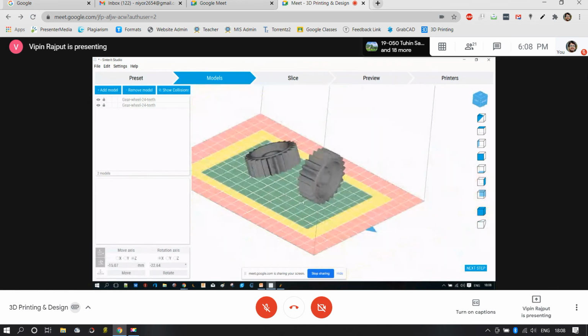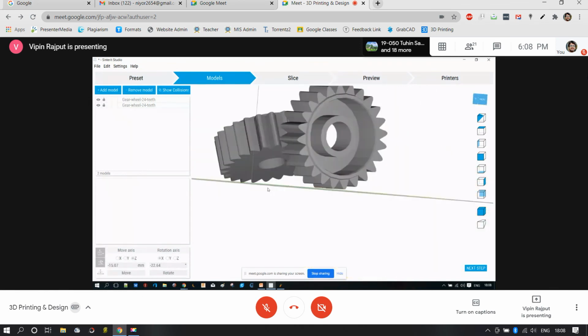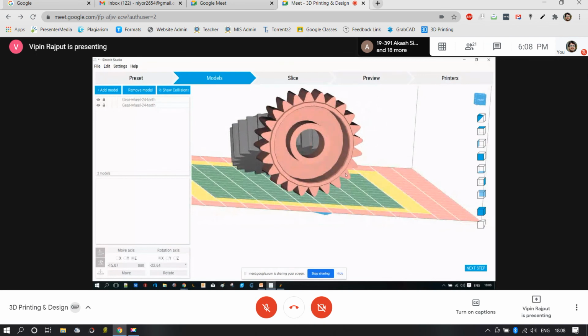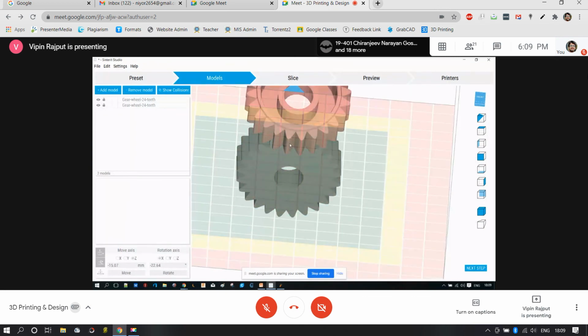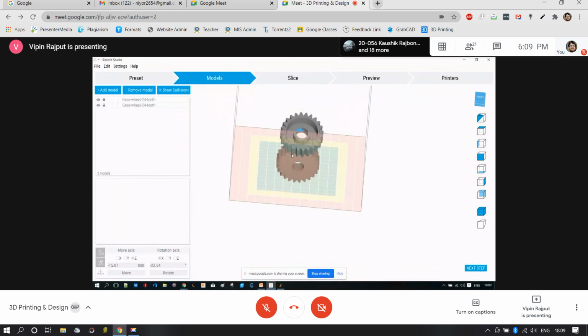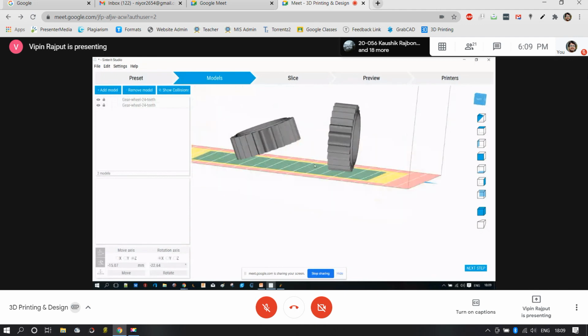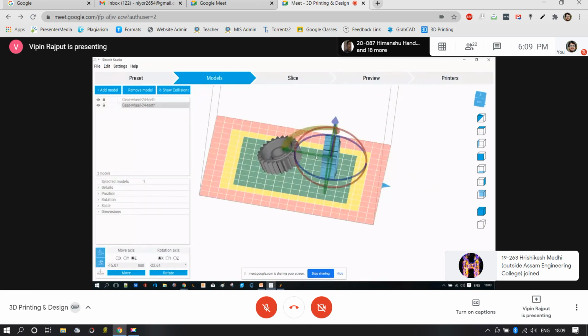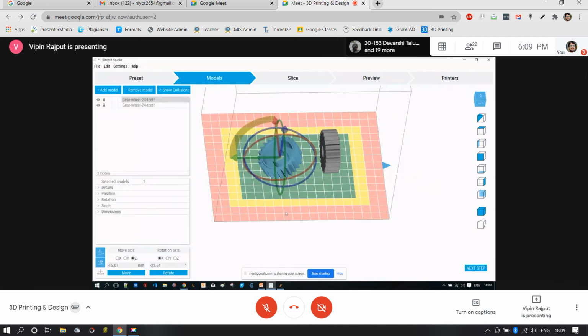Before predicting, just make sure that in this particular orientation all the hinges are separated, the overhangs are at different places, and the point contact is not on a greater side. Keeping all the parameters in mind, now you let me know. This is 2, this is 1. Which one? The inclined one.